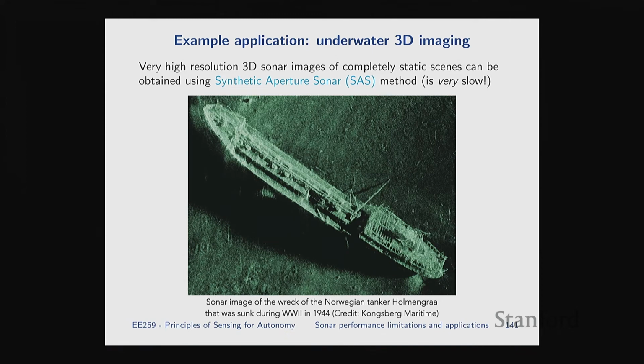But this picture can take hours to collect all the data, because they're very slowly moving their transducers underwater. It also requires a very high amount of compute to generate. It's all done in post-processing. So it's not like a live view where you're going to get this image. No, this is hours of data collection, maybe another hour or two of crunching the data, and then eventually you get this. Again, not useful for robotic autonomy, but just so you know, sonar in other applications can do very high resolution things. Any questions?